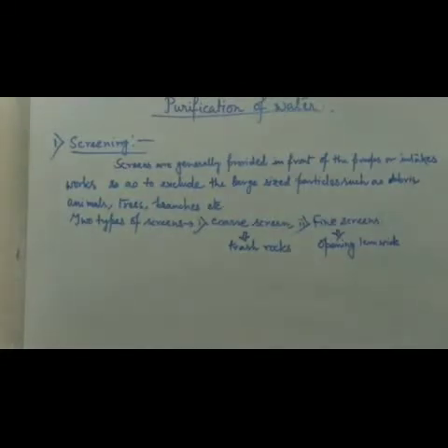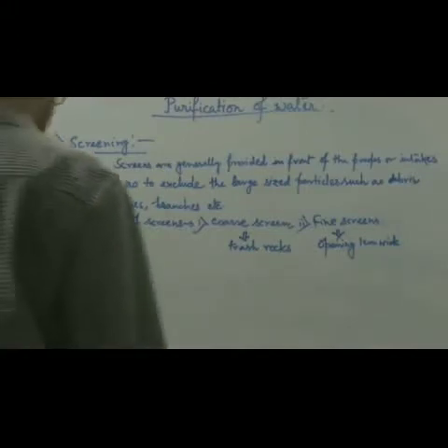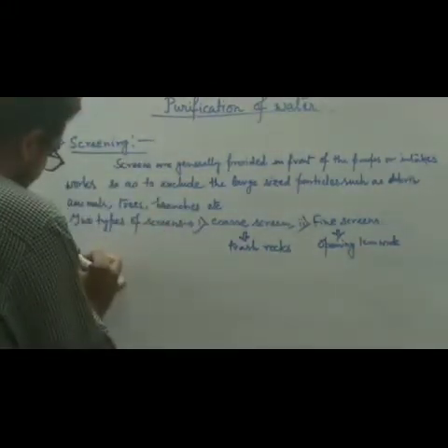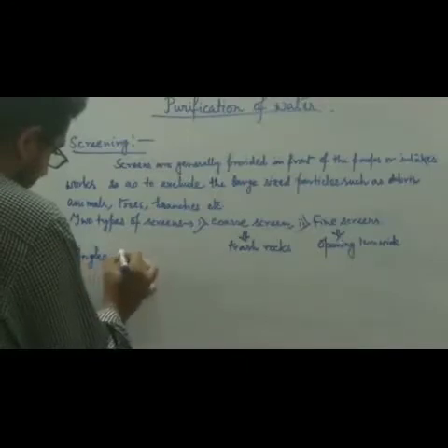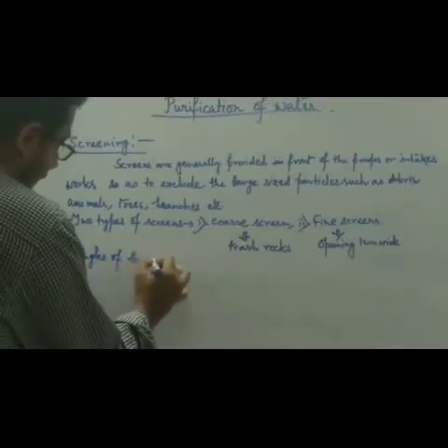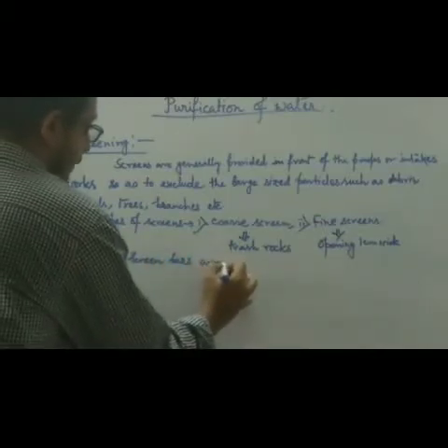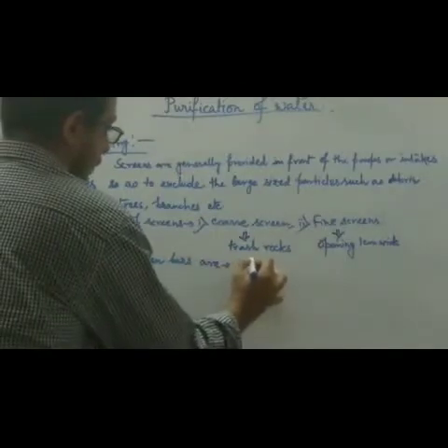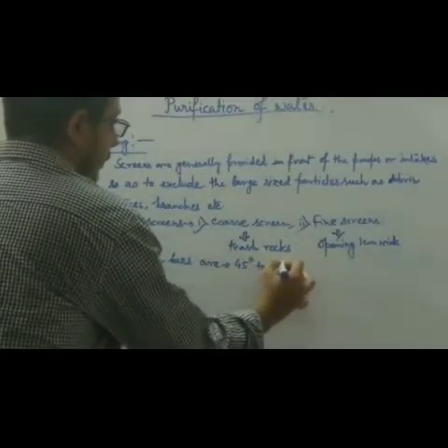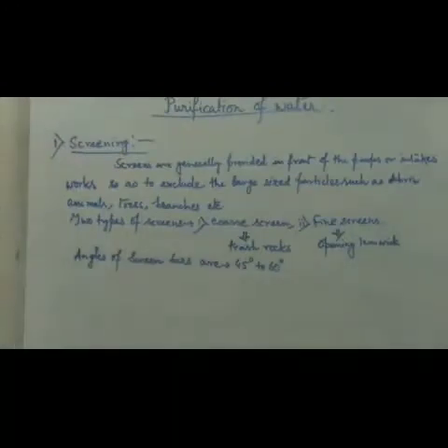Now these fine screens are sometimes set at an angle, and this angle is 45 degrees to 60 degrees. So please write down, the angles of screen bars are 45 to 60 degrees.